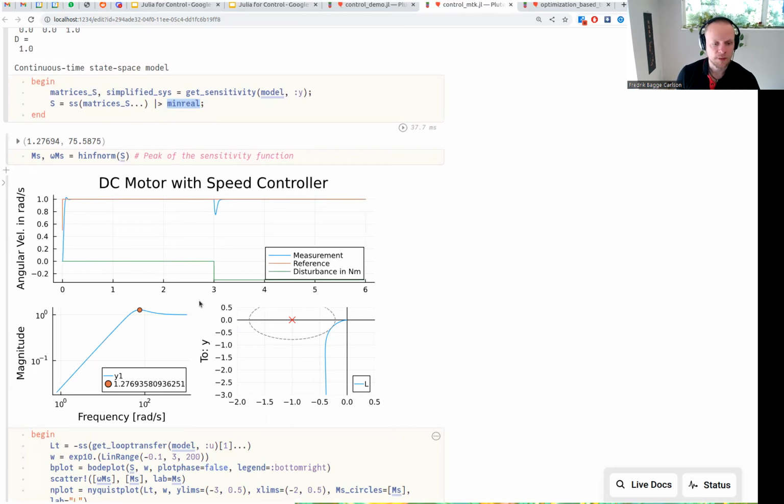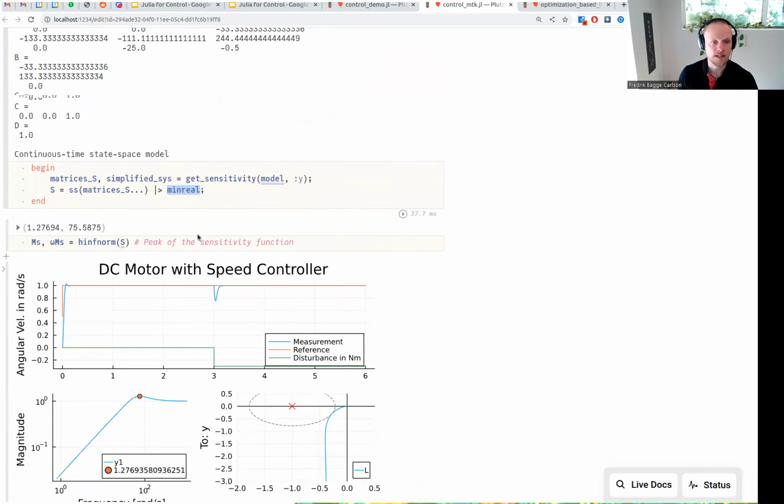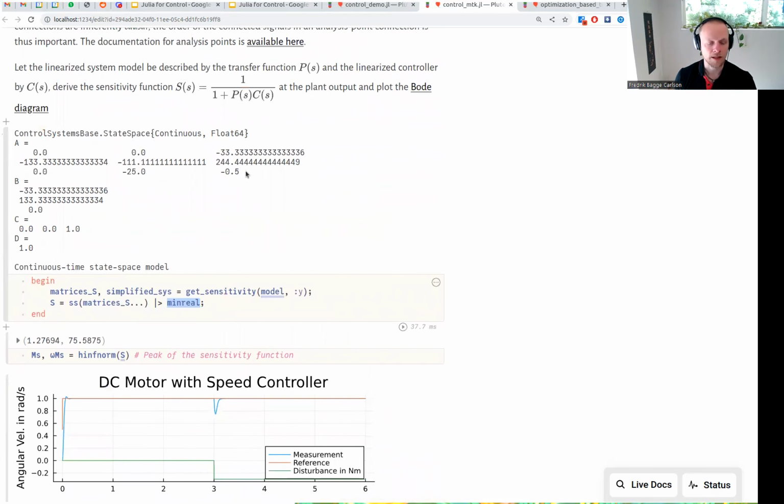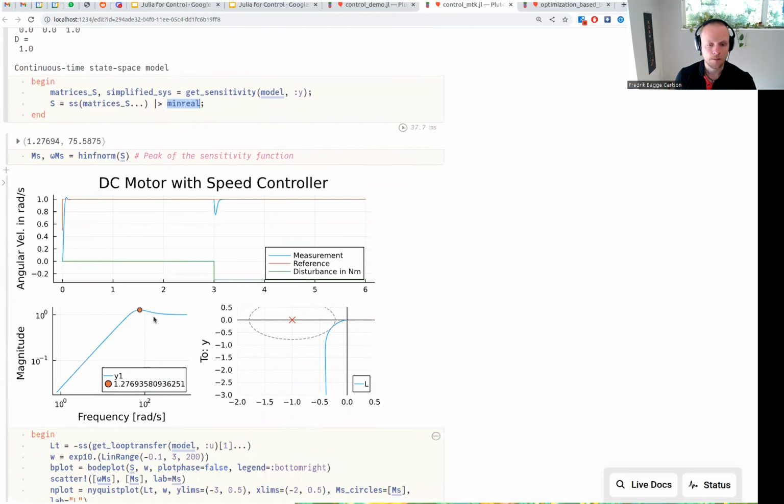So this kind of interface makes it quite convenient to query your nonlinear model for typical linear classical robustness margins. And we can use this to quickly get an intuition for if I change the parameters of my model, if I change the parameters of my controller, what will be the performance using a simulation, and what will be the robustness properties using classical frequency domain techniques.